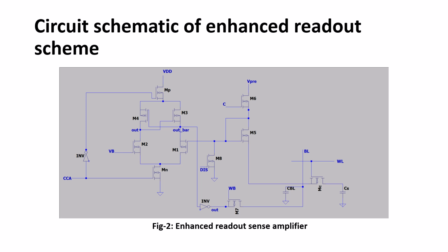Now the voltage coming from the drain of this M5 transistor to this M1 transistor will turn on M1 and some current flows through it, and this overdrive voltage is greater than that of the M2 transistor, as it is only 650 millivolts and this is 670 millivolt.